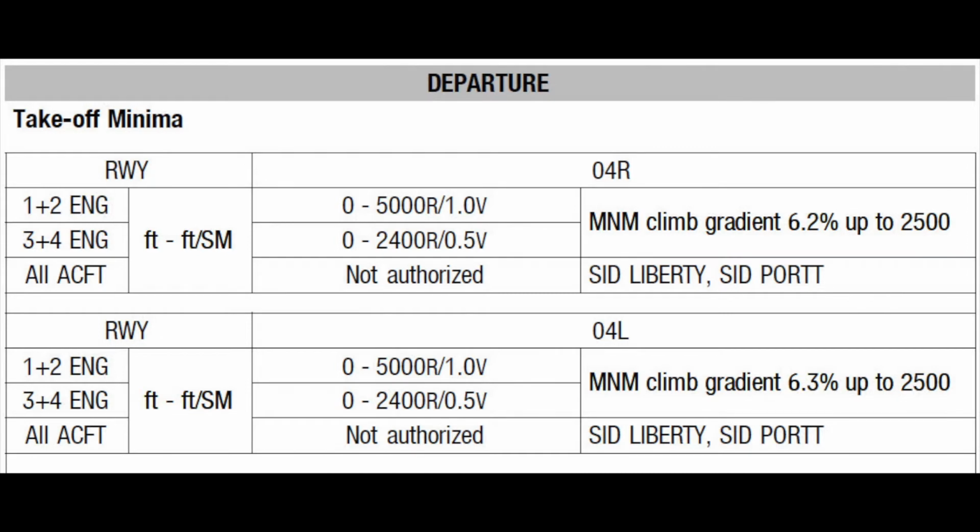Where more than one takeoff minimum is published, the additional takeoff minimum and its dependent climb gradient will be displayed when no climb limit is stated, a continuous climb above 1,500 feet above airport level is required, the climb gradient is 7% or more, the aerodrome elevation is more than 5,000 feet above mean sea level, or an omission of the takeoff minimum climb gradient would cause an operational impact.